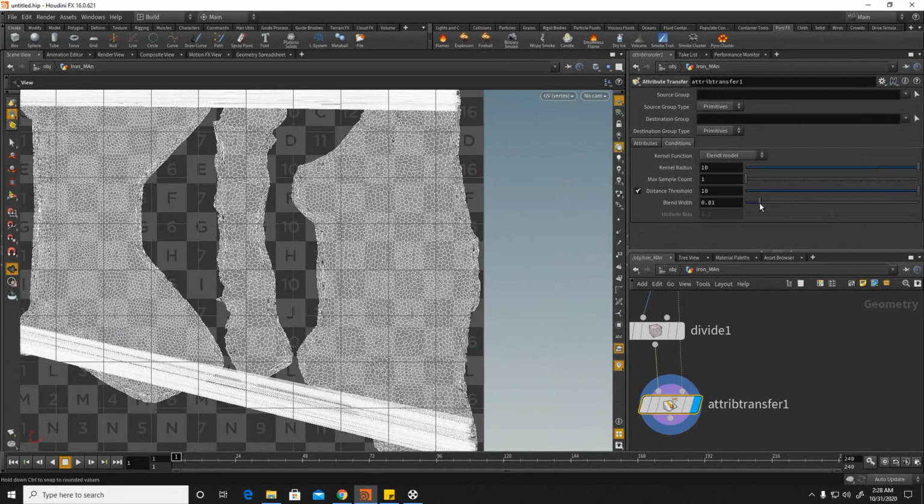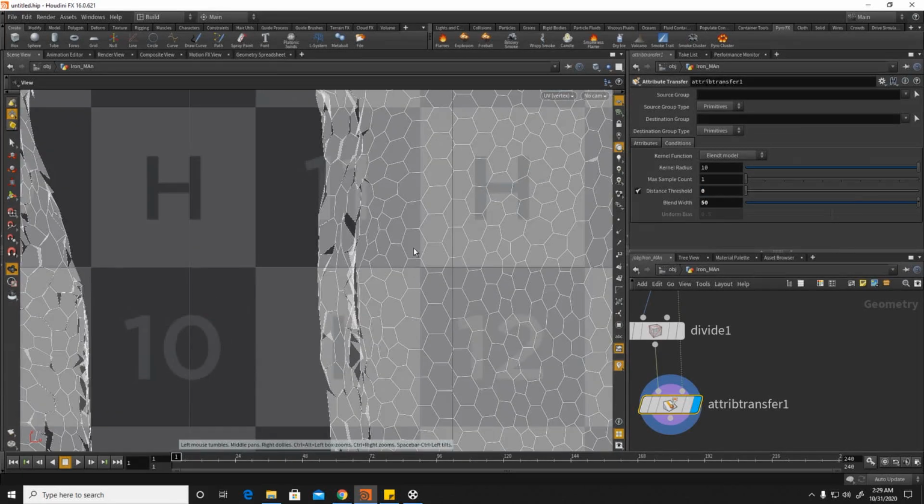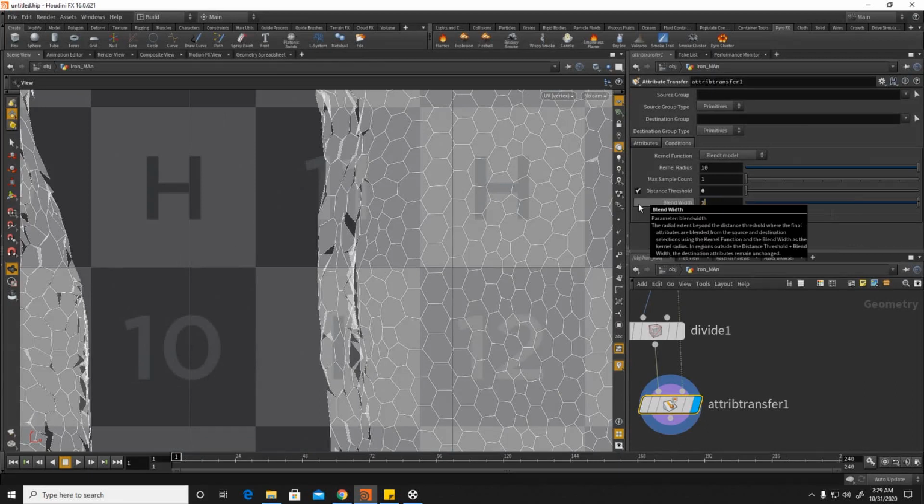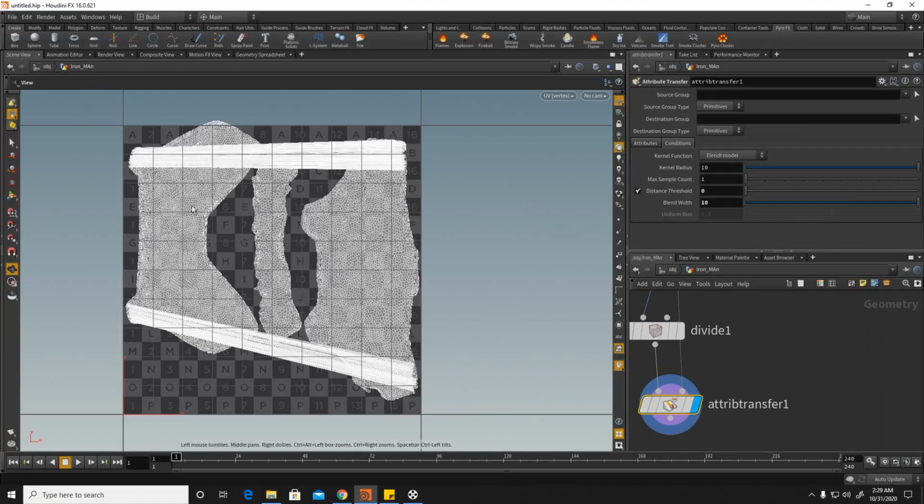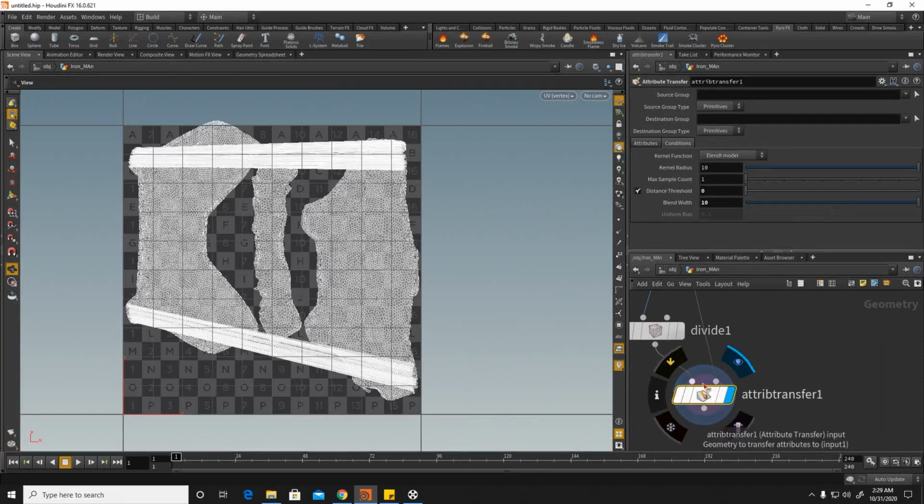We can increase this threshold value and the other value to its maximum. We can make it 0 and this 100, but it will take much more computation time. Sorry, 35 or 50 is enough. Actually it is not impacting that much, so let it be 10 as the geometry is near to it. 10 is quite enough.